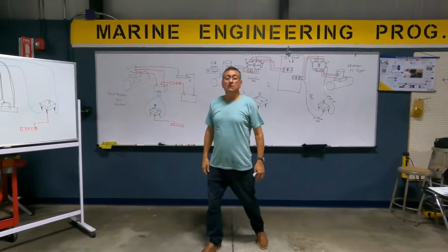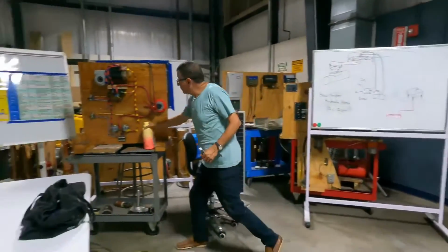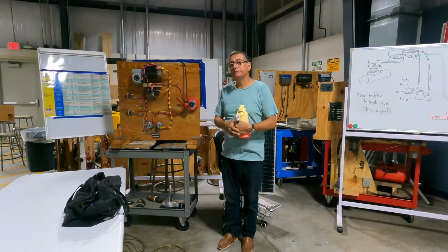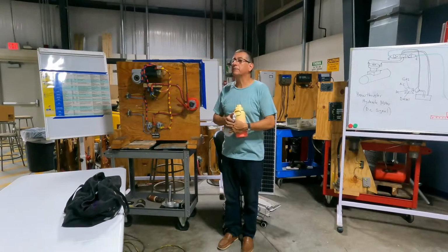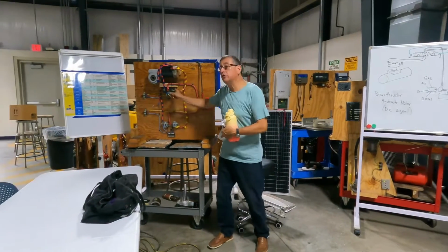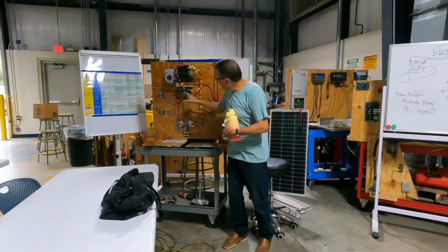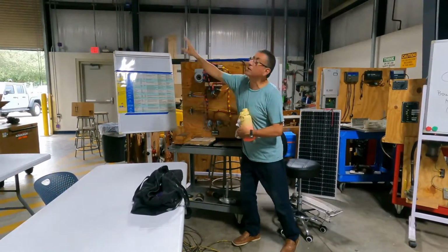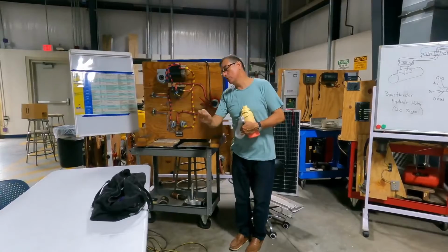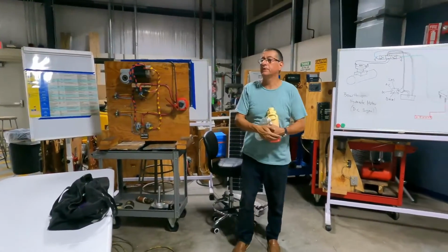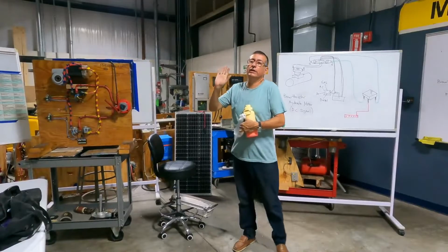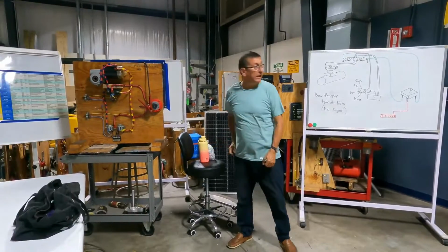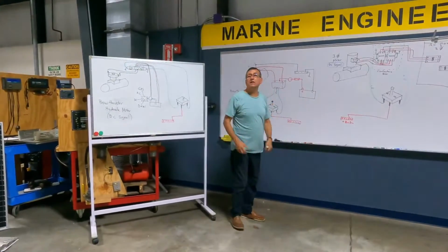Solenoid control box out. I can replace the solenoid control box with a couple of relays. And bingo, finito. I solved it. Oh, the solenoid control box is good. When I power it here, probably it's the harness and probably it's the remote switch, the joystick or the toggle switch or the push button. Or the wire carrying the signal, right? Correct. Or the harness. Good? Alright. This is the traditional DC bow thruster.